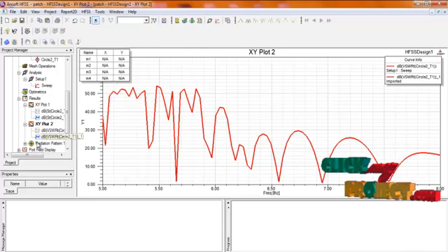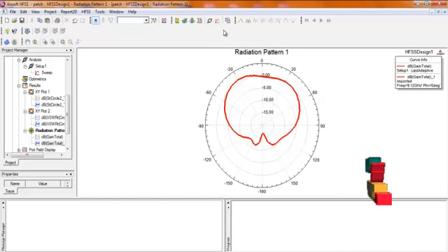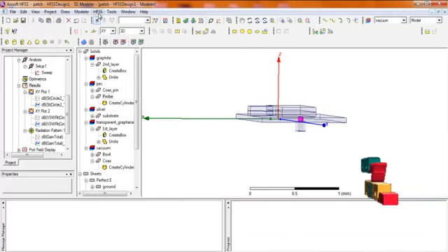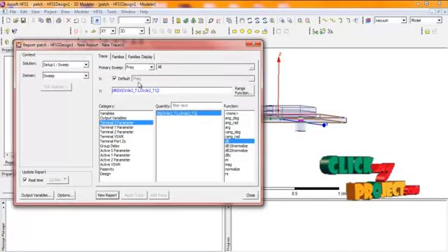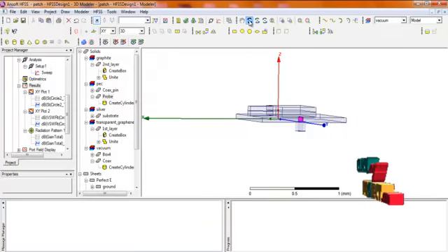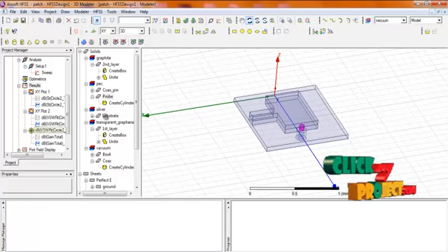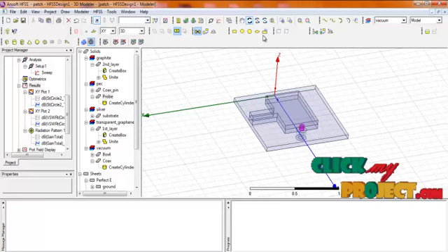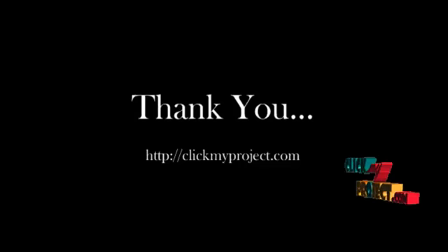Whatever is calculated, the VSWR is calculated. And then this is the 3D and the 2D radiation pattern. Here I will select the frequency. Then I click the results, HFSS results, and the rectangular plot. I am using the return loss graph. And then the overall graph is shown. This is the design that I made. These are the 2D and these are the 3D plots. So these are the overall running procedure for the process. Thank you for listening to this video.